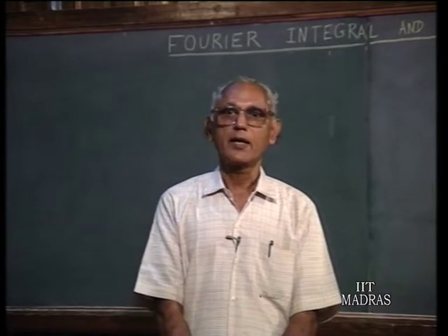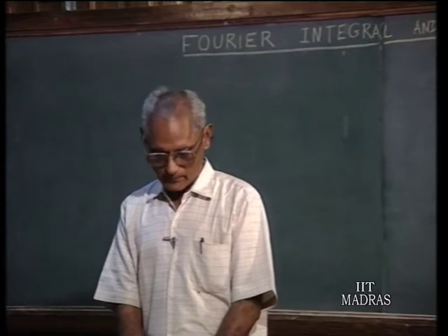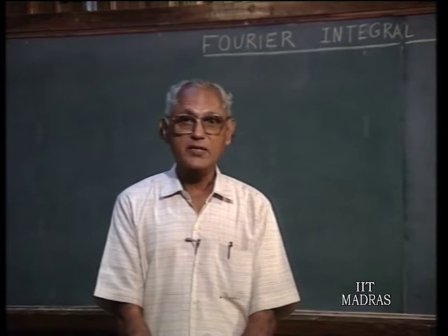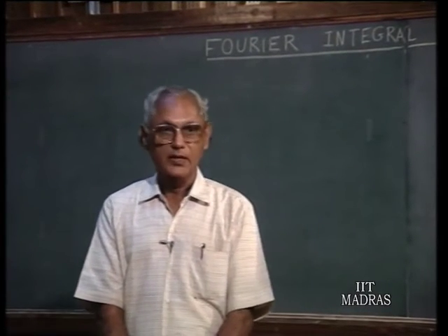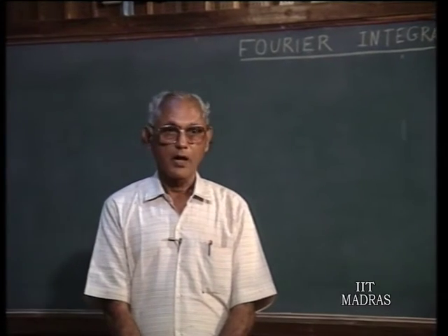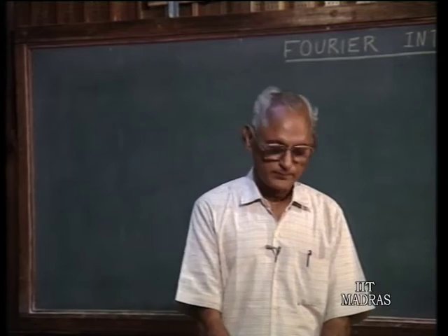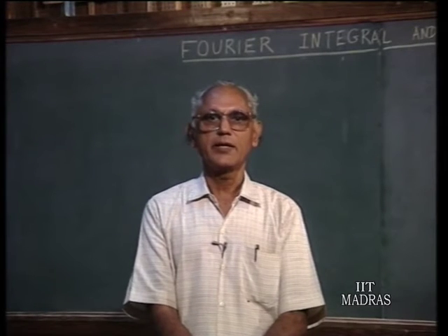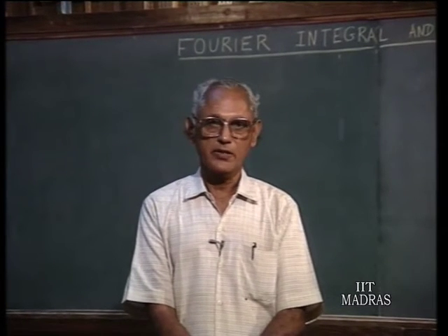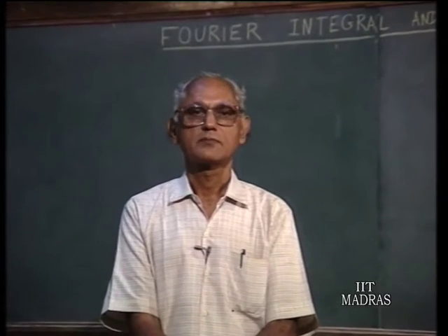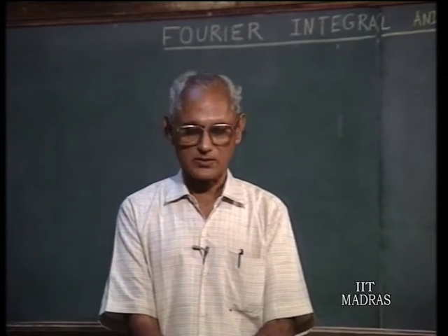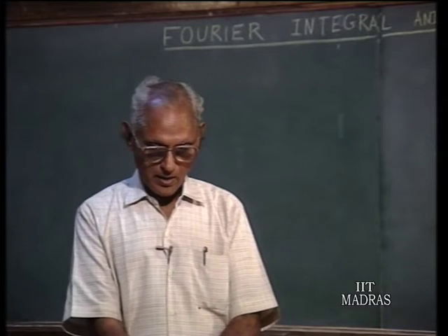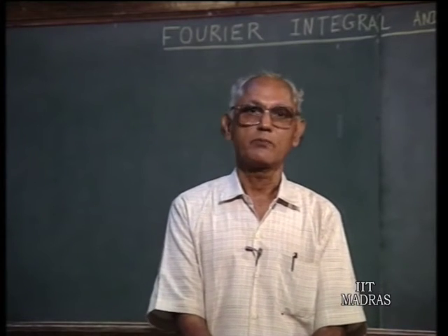how we can analyze a linear system when it is driven by a periodic non-sinusoidal excitation function. And the Fourier series came in very handy in that context, in the sense that any non-sinusoidal periodic function can be thought of as composed of several sinusoids of different frequencies, and by virtue of linearity principle we can find out the response to each one of these excitation functions and superpose the responses to get the total response under steady state conditions when the linear system is driven by a periodic but non-sinusoidal excitation function.